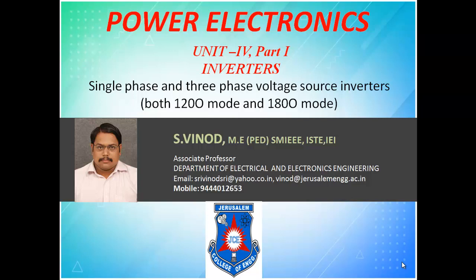We were talking about the various types of switching devices we have seen in unit number 1. Among that we came to a conclusion that there are two types, current control and voltage control. Current control devices are suitable for some types of application and voltage control devices are used for others. In current control, wherever you convert from AC to DC, you can use current control. Wherever you use DC to DC, you will go for voltage control.